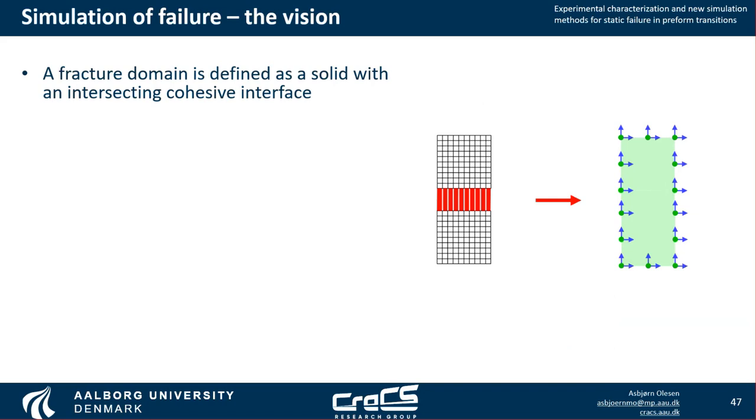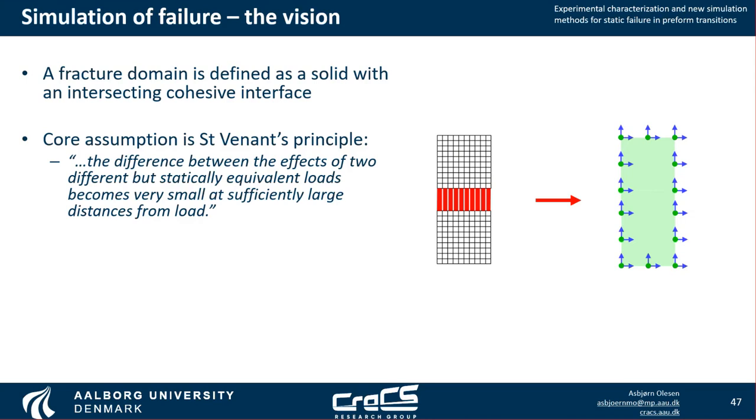Getting a little bit more into the specifics of how we want to approach this is that we define a fracture domain. This is defined as a solid with an intersecting cohesive interface, as shown here in the red. The core assumption that we're working on is what's called Saint-Venant's principle, where it can be stated as the difference between the effects of two different statically equivalent loads becomes very small at sufficiently large distances from the load.